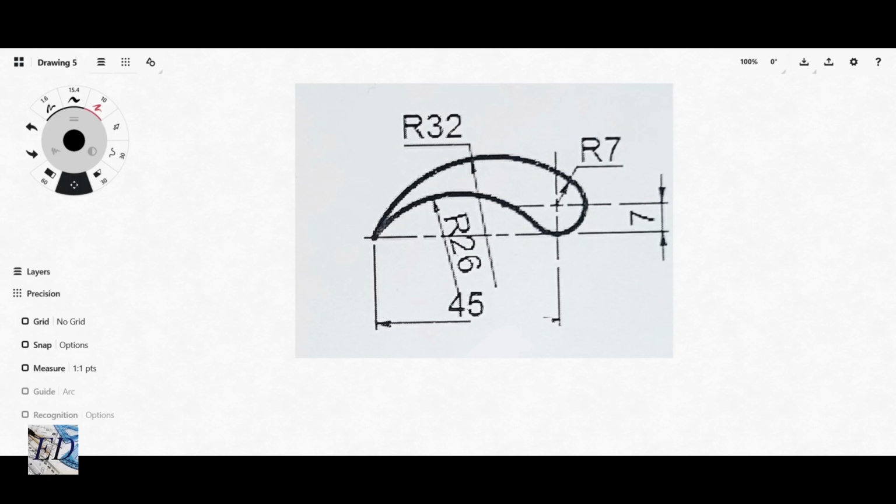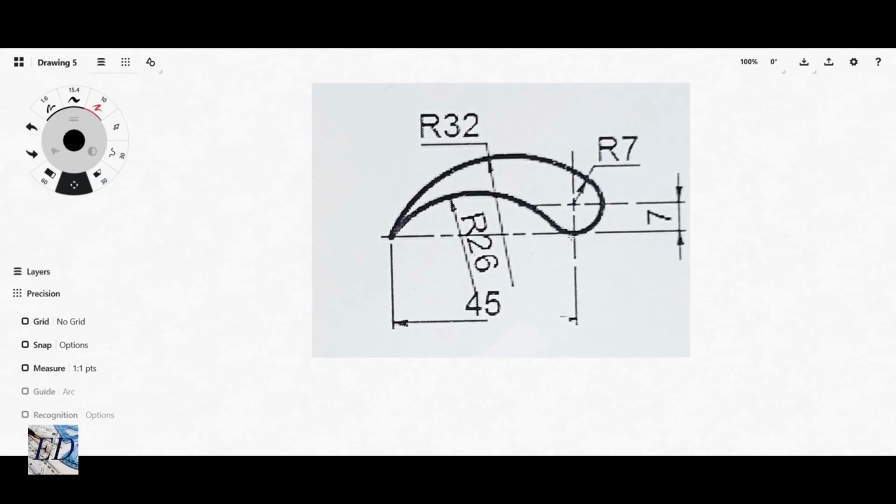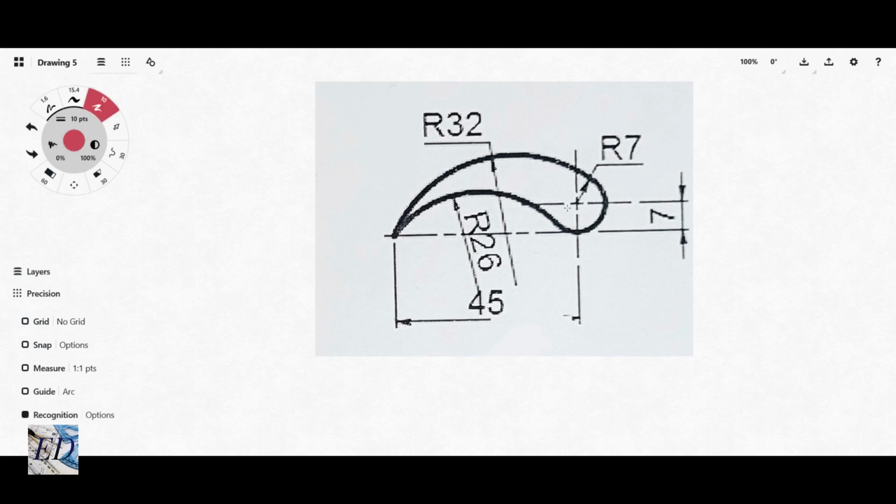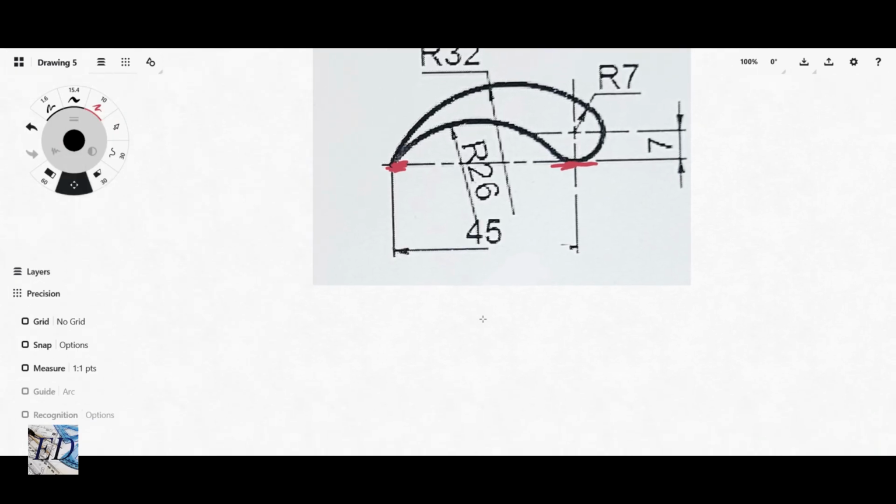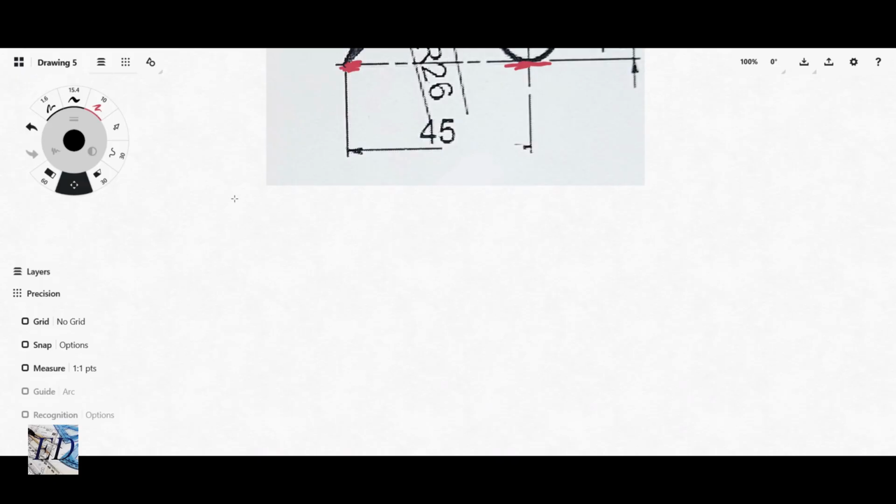Once again, this circle falls on this line, exactly on this point on the line, and this particular one, both of them have some relation with this point, right? So I would start off with the center line, because that is the easiest to draw, and that solves the issue when it comes to location for most of the features.